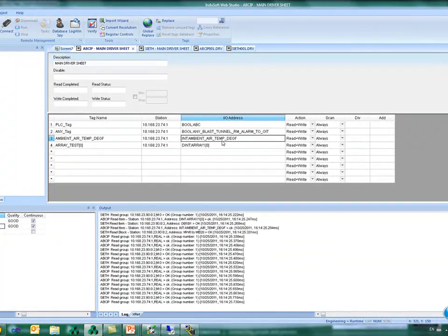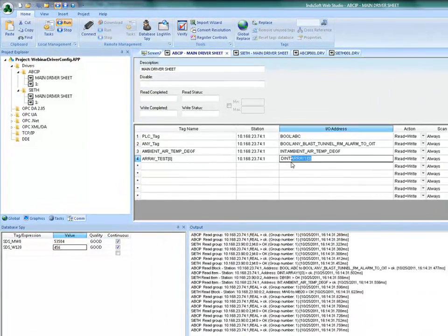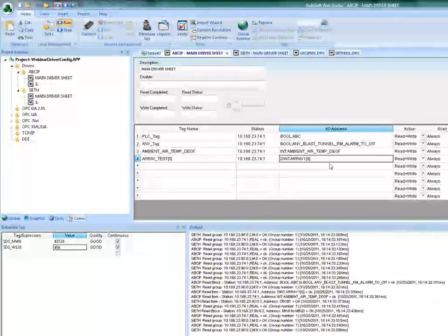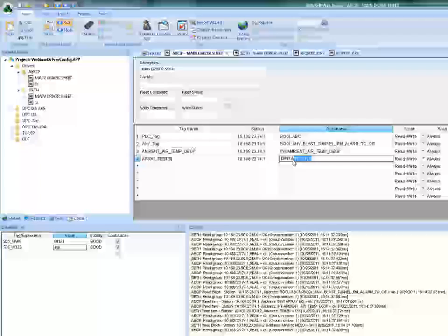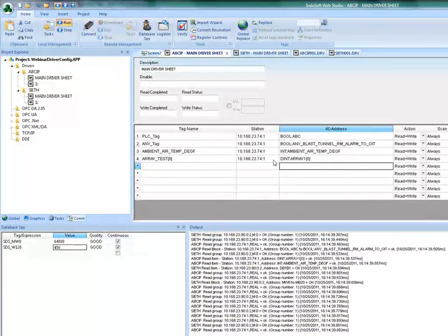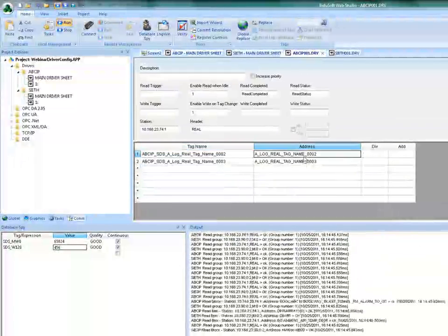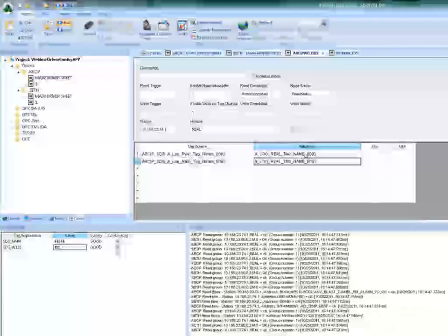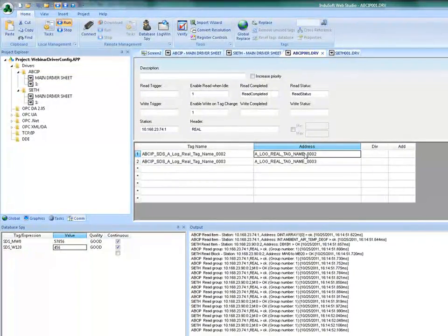Okay, so here's the hint on Allen Bradley: use arrays, keep the tag name as short as possible, and use multiple connections. You're gonna have the best communication possible. If you use several tag names with long tag names, you're gonna need to send more messages to the PLC, and that's gonna slow down your overall communication, because you're gonna need to go to each worksheet at a time.